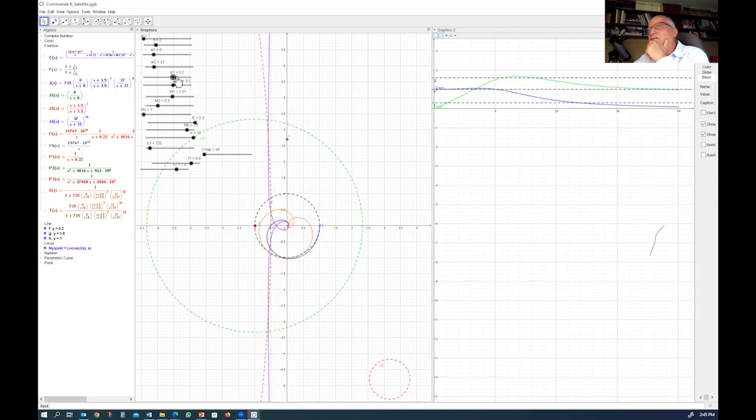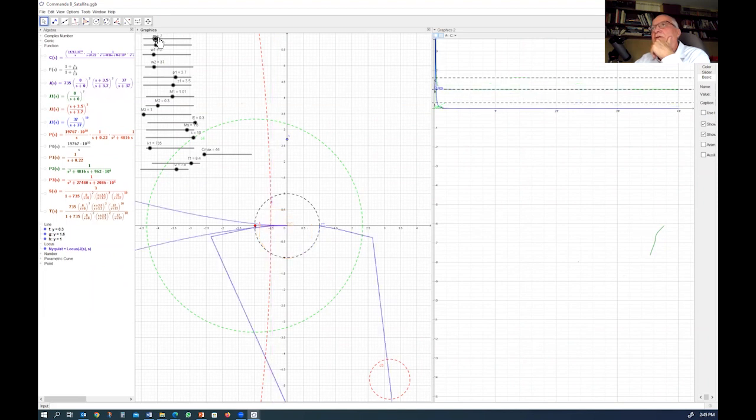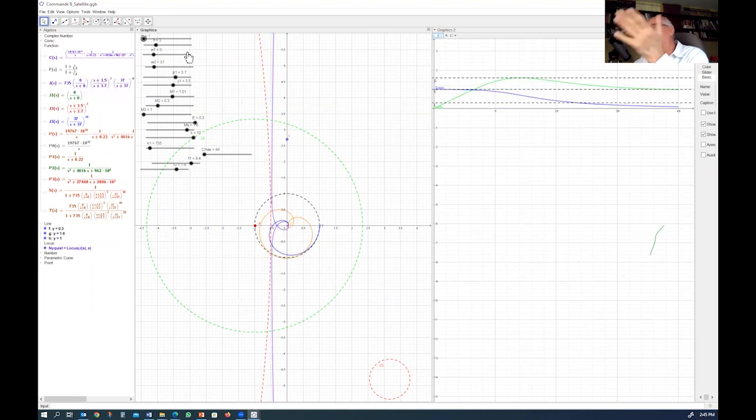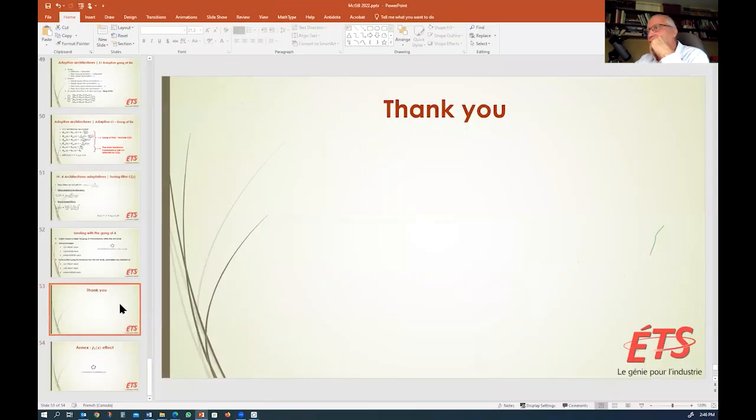So this is for fine-tuning of the time response. There is also the pre-filter, and we can play with it and try to adjust it to have better results until we finalize on this plane. We can finalize the frequency performance, and we can also present here the time response. And with that, I think I finished and I'm ready for questions.